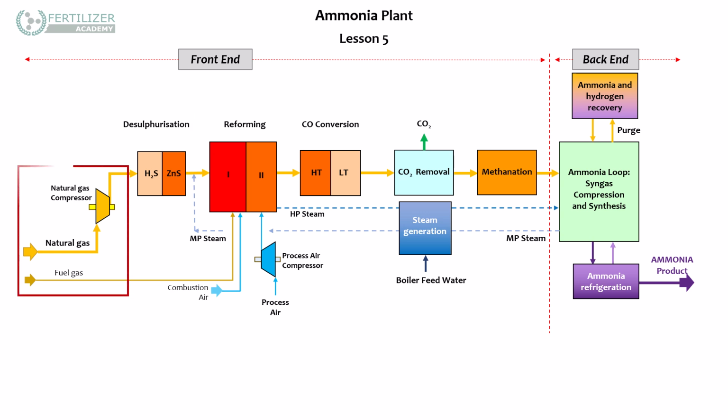Lesson 5. Natural gas compression. In this lesson, we will focus on the natural gas compression unit. This section receives the feed gas stream after it has been separated from the fuel gas and delivers it at the required pressure to the desulphurization unit, followed by the reforming section.